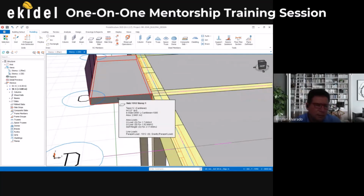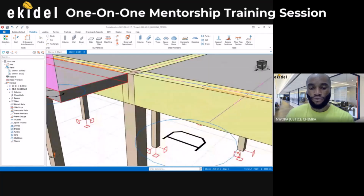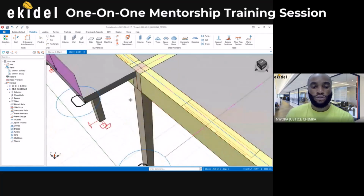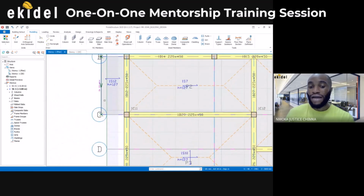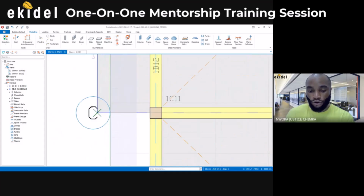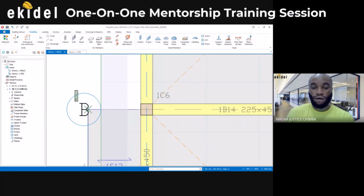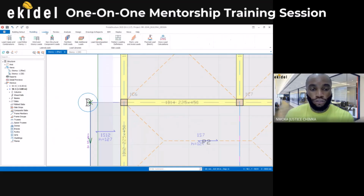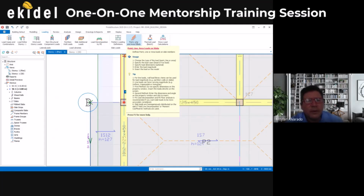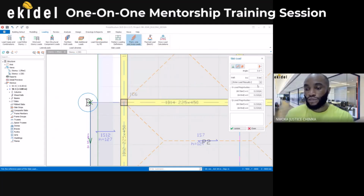Yes. So if I want to add this same load now on this other side of the slab, what I would do is to come here, although this one alone is already okay. But if you want to add your own load, for example, on this line now, and not on these lines too, what I will do is come to my loading here, and then I'll see line load. You can see here point load. Okay, point loads, line loads. I'll click on line load, and then I'll come here.